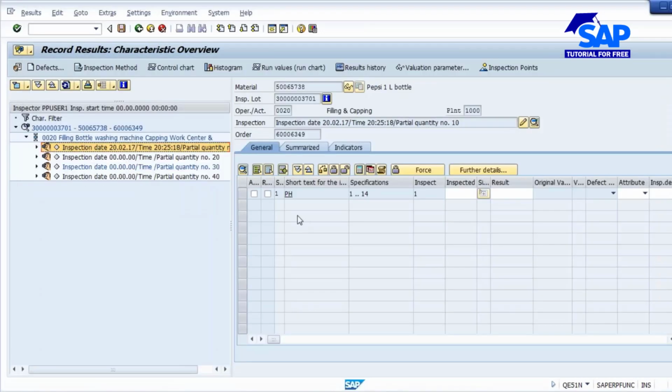That means after producing every 250, you do a quality check. So when they start the production, once the first 250 is produced, you as a quality person go take one sample, inspect it, come here, and enter the result for this inspection point. After producing 500, production people will inform you, you take some sample, do inspection, and enter for the next inspection point.